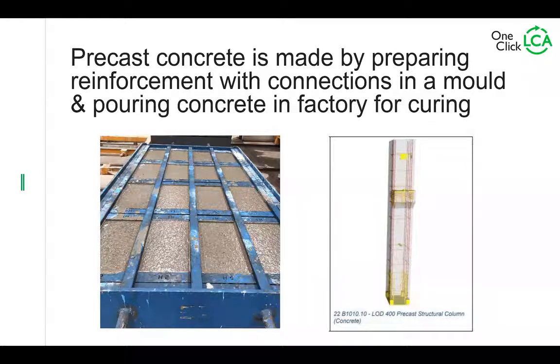So some concrete plants use Friday batches. The Friday batches use less cement because they are left to cure over the weekend for the initial curing before they are lifted.